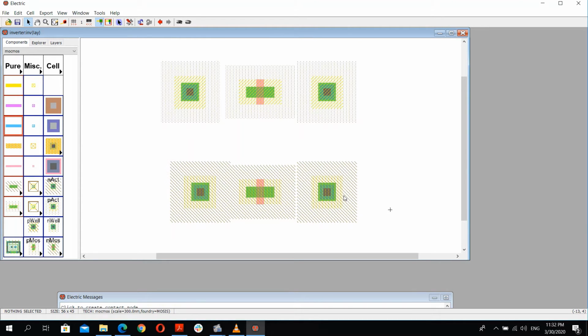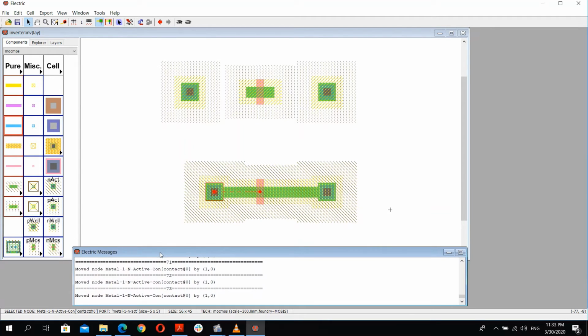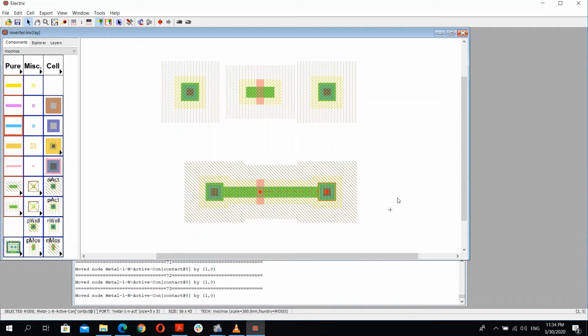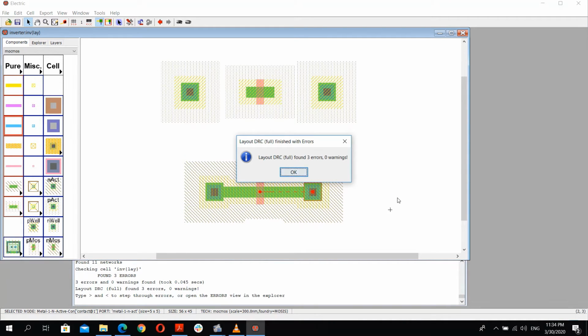As we were making the connections in the schematic view, here in the layout view we left click on what we want to connect. Then we right click on the other side, and then we have a connection here. Same goes for here. Okay. Then, by pressing the right arrow or the left arrow, using the arrows, I start to get this closer and closer to our transistor. As I said, we start to get this closer and closer to the transistor, and each time we run a DRC to check if there are any DRC errors in this area.